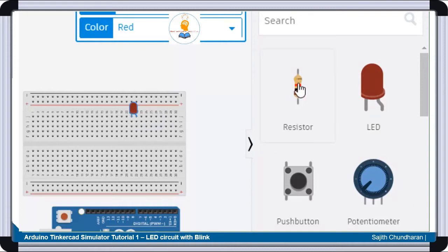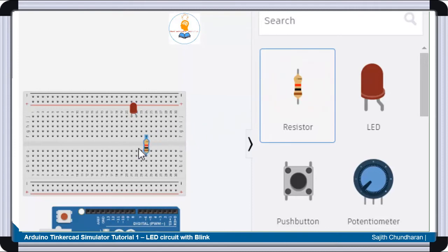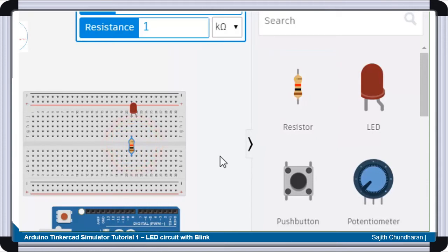So for the resistor, once you select it, you must drag and drop it at the cathode line. You can see that that is the cathode line. You can put it anywhere near that, but don't put it anywhere else. Just down the cathode line you have to connect it, and ensure that you are not putting the resistor like this because it remains the same point. So always put it across so that it is at different points. Right, so the resistor is also in its place.